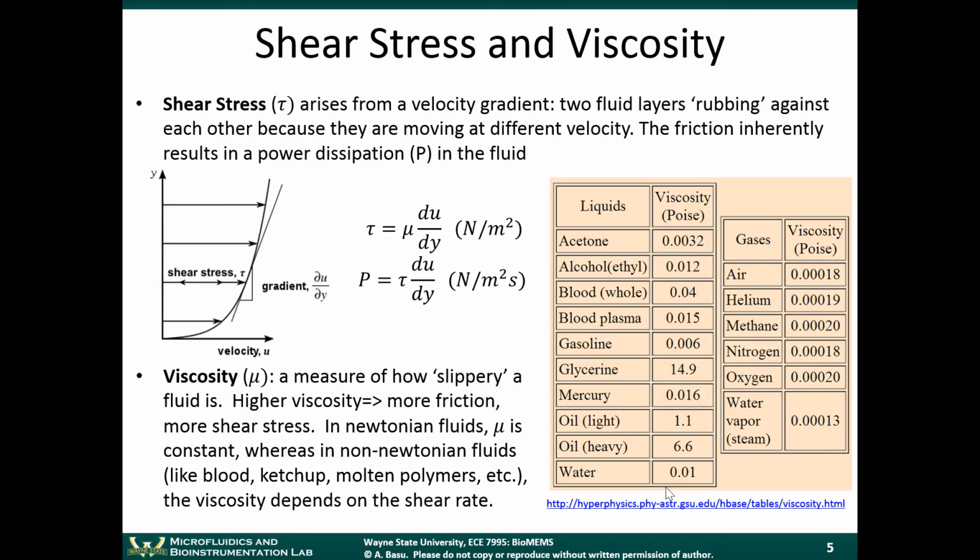So imagine that we have a block of fluid here. So that cube is sitting right here. The top of the cube is going to be moving at a faster velocity than the bottom of the cube, right? So that's creating that shear stress, that sort of rubbing motion. Velocity on the top is faster than the velocity at the bottom. So that fluid element will be experiencing shear stress. That is the origin of the shear stress that you see here.